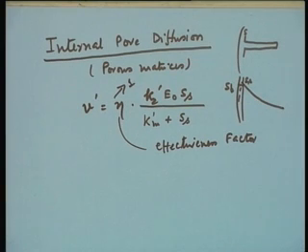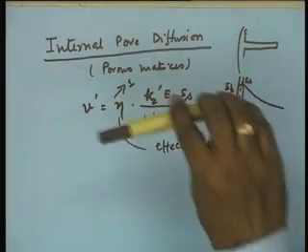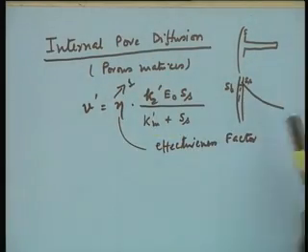That is the ultimate limit, and normally the internal pore diffusion effects are described by the effectiveness factor. Now, I think there is a very tricky situation. In many cases people have also reported effectiveness factor exceeding unity, from experimental observations. Say you measure the enzyme activity for different particle sizes in a reactor, and the effectiveness factor works out to be more than 1. Under what conditions should the effectiveness factor be more than 1?